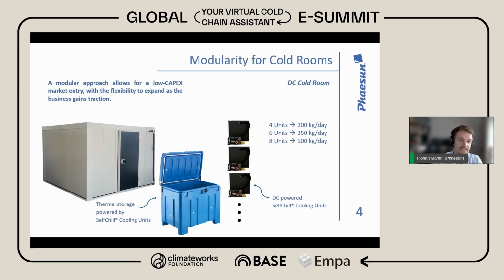And how we implemented this with our DC-powered cold rooms with the self-chill technology that we have developed using thermal energy storage, where you can put a number of cooling units, starting with a certain cooling capacity, and after time you can just add more and more cooling units to the same thermal energy storage, the same cold room, and thereby increasing the cooling capacity later on.